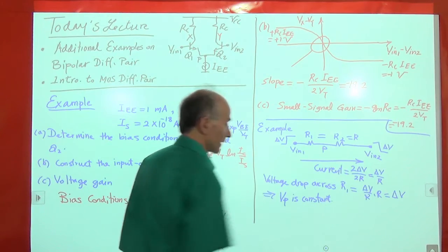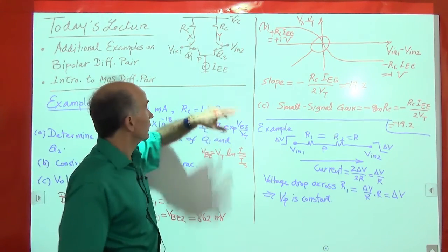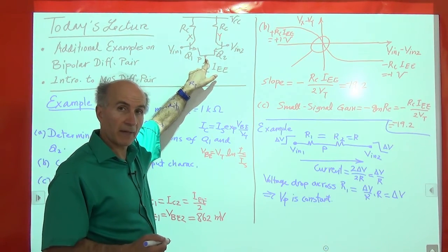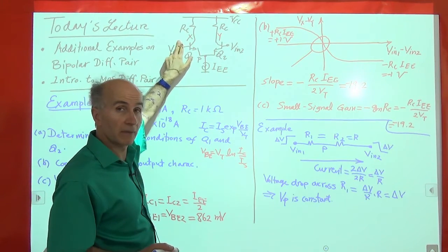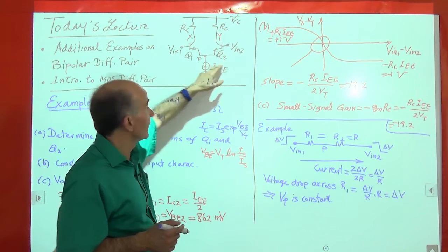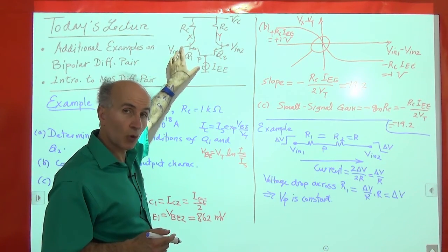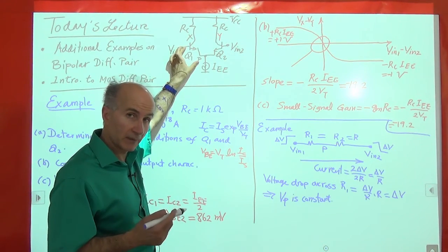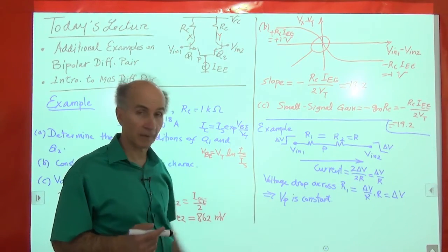So this is similar to our analysis in the previous lecture about this node P, right? We also saw there that after we did the calculations, if this goes up by delta V and this goes down by delta V, and those are small values, then that delta V is entirely absorbed by VBE1, meaning that VBE1 goes up by delta V, so this node does not have to change. And it's the same story here.